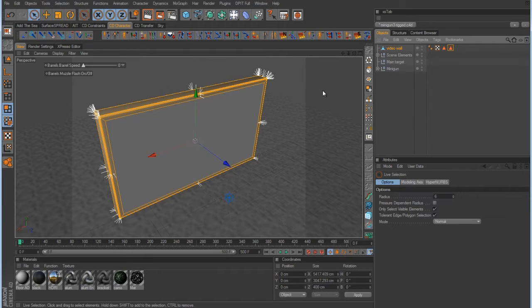Now, in previous versions of Cinema 4D, which I don't know if any of you were actually using them, but in release 9, when R9 first came out, Maxon had a really nice little feature here that whenever you made a set selection tag and you typed in the name, it would automatically deselect itself. That way, if you want to make another set selection, you didn't have to come up here and deselect the tag and then click the object again in order to make another set selection.